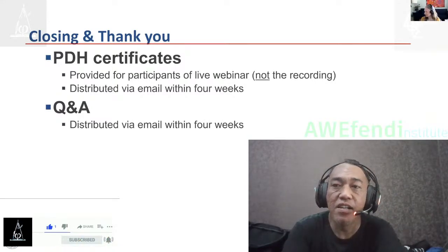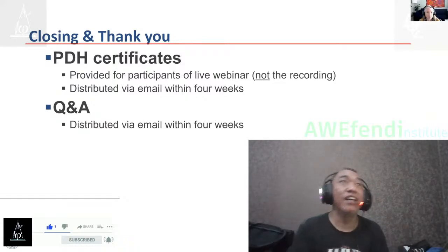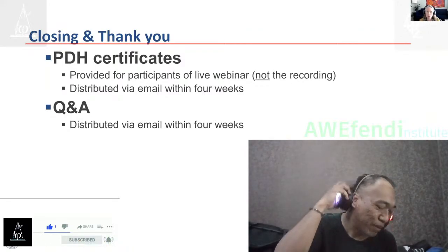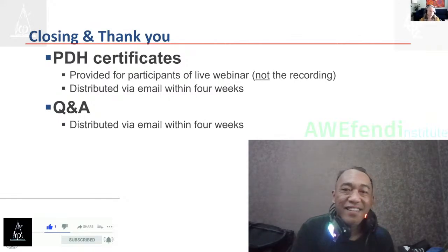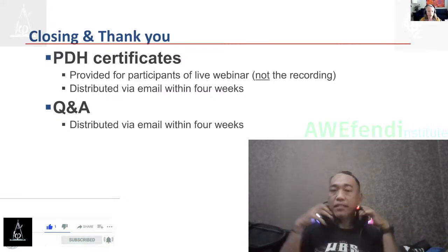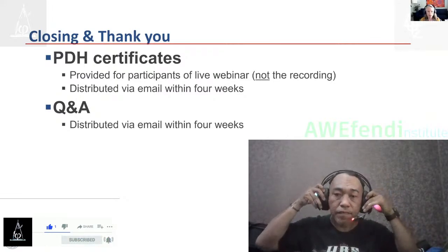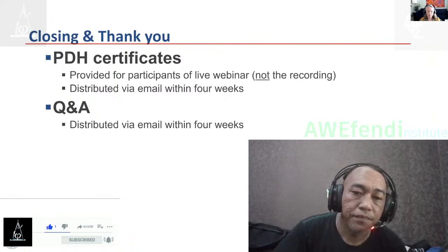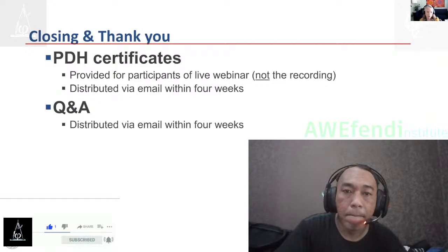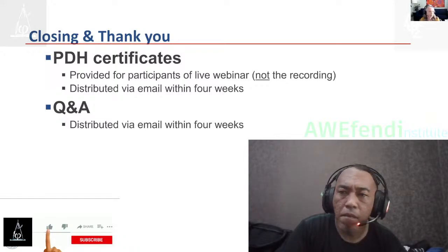Great, thanks, Mike. All right, let's see if we can squeeze 1 more in. So this one is for a reentrant corner type diaphragm. It used to be a 15% projection, but now it has been increased to 20%. What is the rationale behind this change? And one of the reasons I picked out this question is because there are quite a few questions we received, which is like, in the Canadian codes, it uses 10% for accidental torsion, and we use 5. What's the difference? So maybe just speaking to how these numbers evolve and how they change over time.